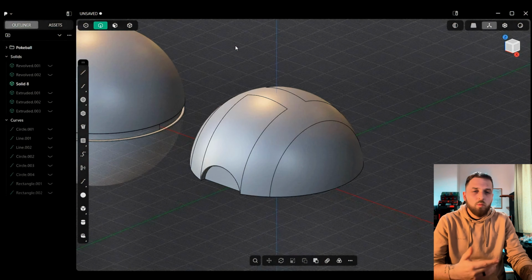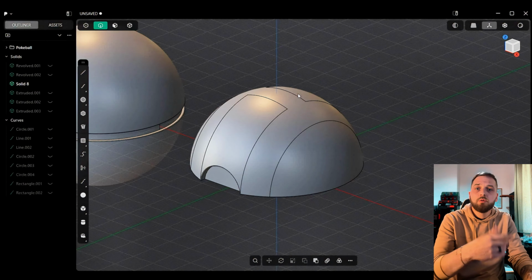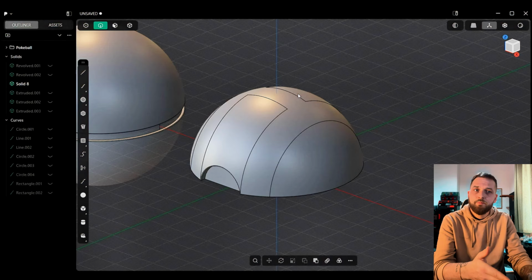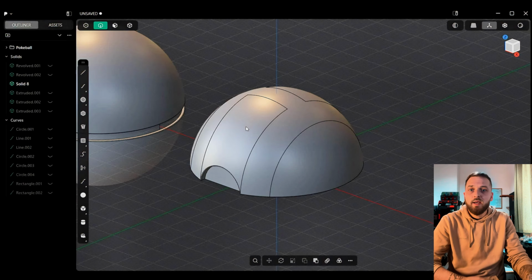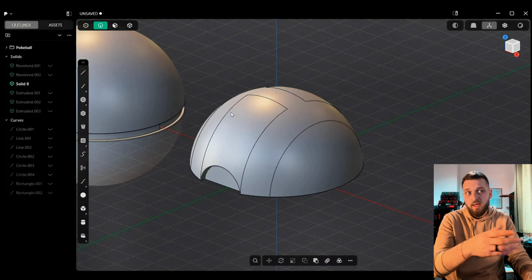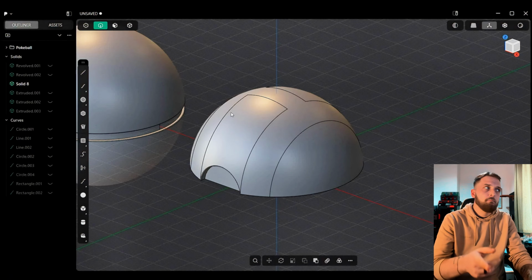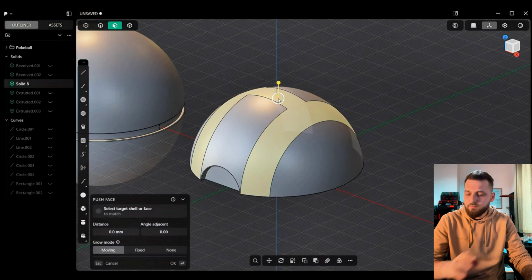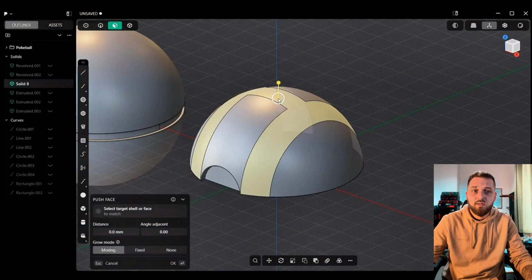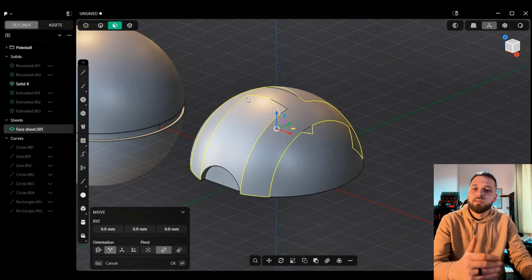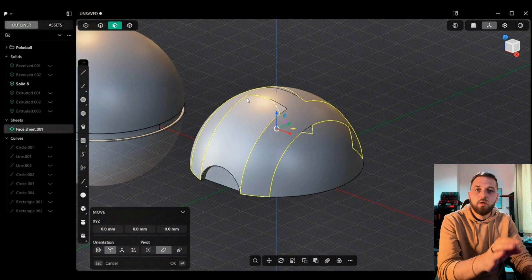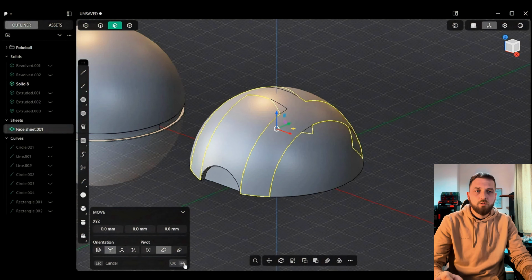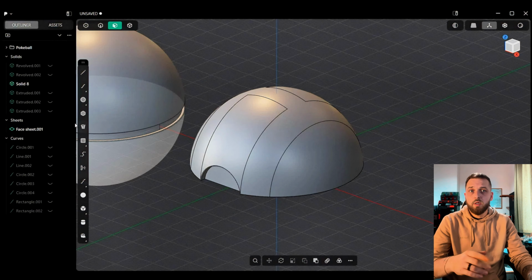Now, there are many different ways of doing this next part. You can just simply go up to the top, use that drawing to cut it down. Then that'll make all these pieces individually. But there's one trick I wanted to show you. Now, if you click on faces, click on the design, what you want to do is Shift D on that. Now, instead of creating a whole new body, it'll create a sheet. Click OK. There we go.